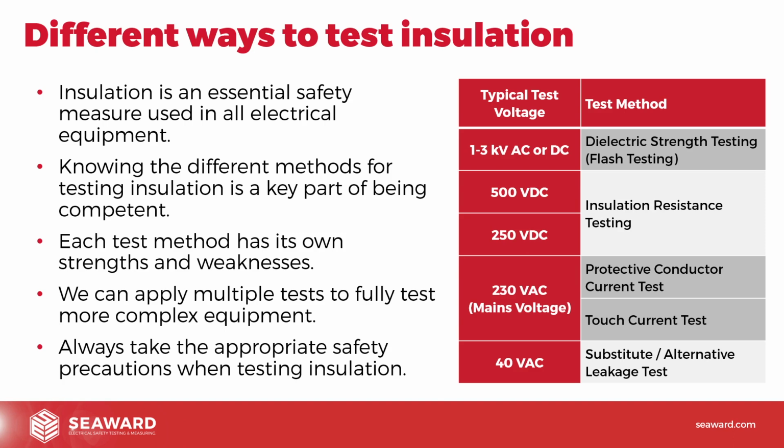Now, that's good and bad, because if we're applying stress to insulation, we could actually damage the equipment. If we've got sensitive electronic equipment and we don't apply the test in the right way, we could damage that equipment by doing a dielectric strength test. Whereas applying something like a substitute leakage test is what we refer to as a soft test. It's not going to actually risk damaging the equipment.